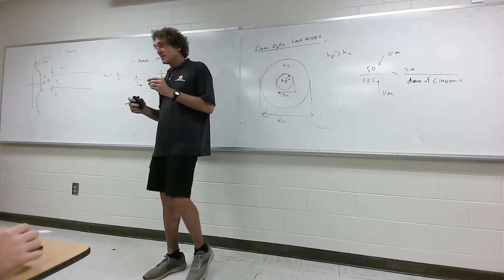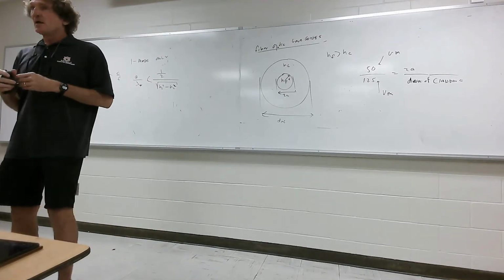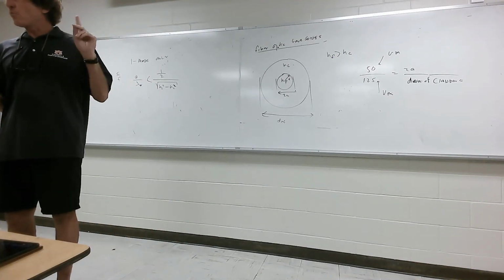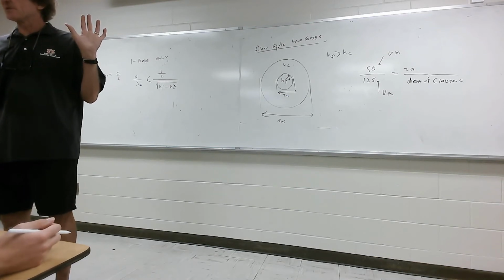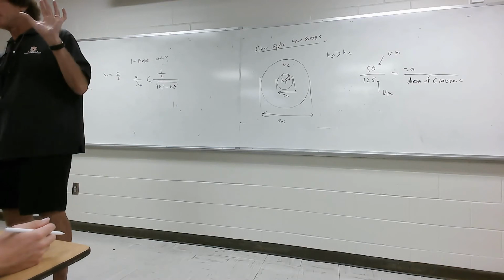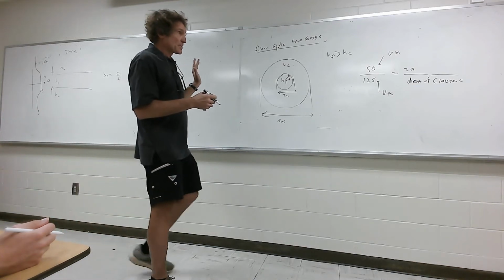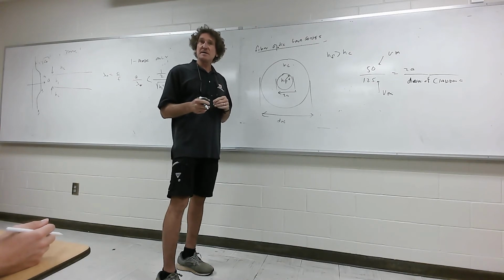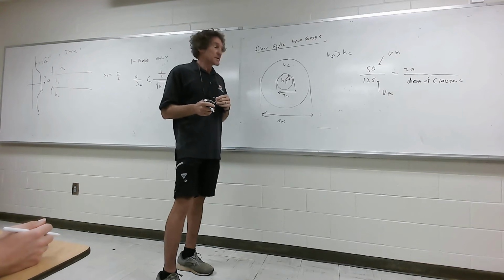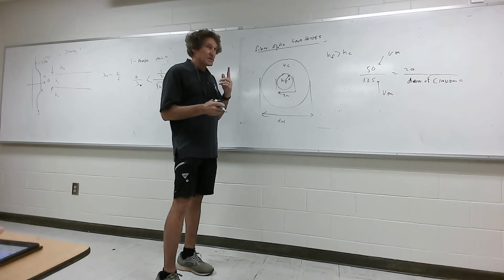But I'll tell you this, he doesn't say it in his book. The lowest order mode there will be the 1-1. It'll be a TM11 mode. We're not going to prove that because it takes a solution of Bessel functions, and I've asked people about this, and they don't feel it's appropriate for this class. You'll see this if you do anything at the senior level with optical fiber. They'll go through the whole analysis. I still may do that. I'm still threatening to do it if I have more time here.